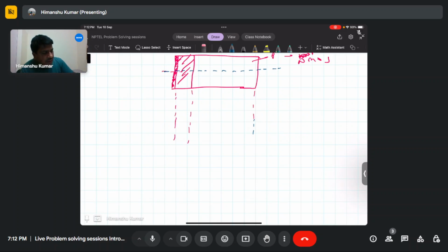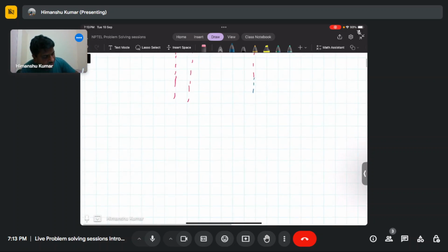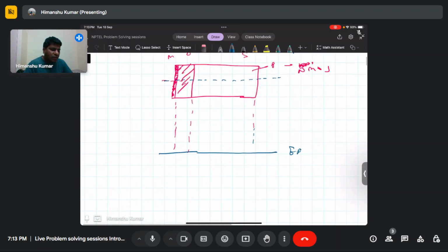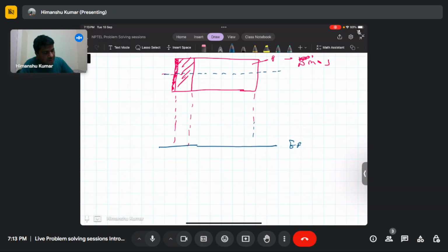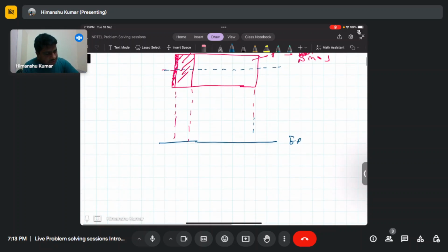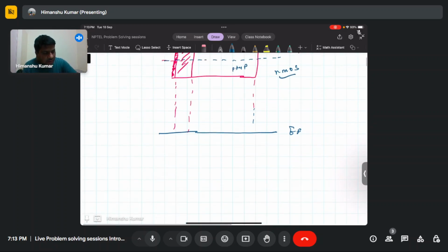So if you want to draw the band diagram, first you draw the constant Fermi level EF, and then you draw the different band offsets in each region. This is P type substrate, for NMOS. So you need to draw the conduction and valence bands, with the valence band closer to the Fermi level.